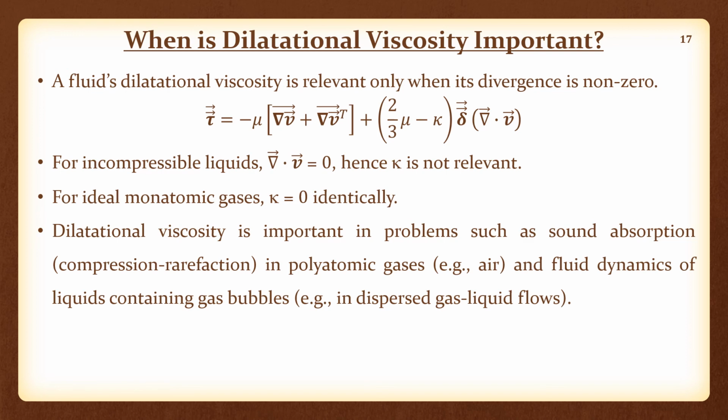So in such problems where you have these gas bubbles, they will be subject to compression and expansion, right? And this would be another situation where the divergence will not be zero, and the gas's dilatational viscosity would come into play in determining the kind of shear stress, the molecular momentum transport that takes place in such systems.